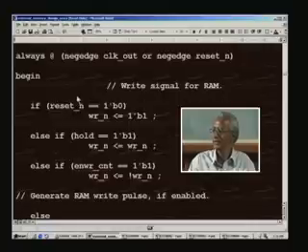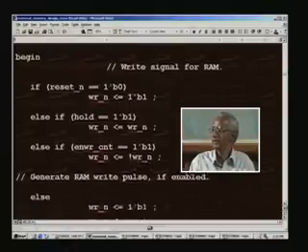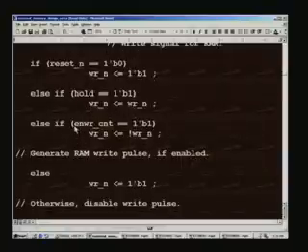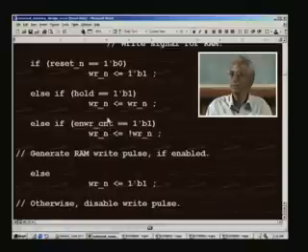And once again these are all the usual reset and hold, and so long as it is enabled, as we have seen before, what we need to do is invert the write. If the write pulse is not there, I mean it is not active, it is in the high position, so we need to clock it, I mean make it low. That is possible by inverting here, and if it is already low, with the arrival of the next clock pulse at the negative edge, this will go high again. Thereby you create at every 2 clock cycles one write pulse which is active low.